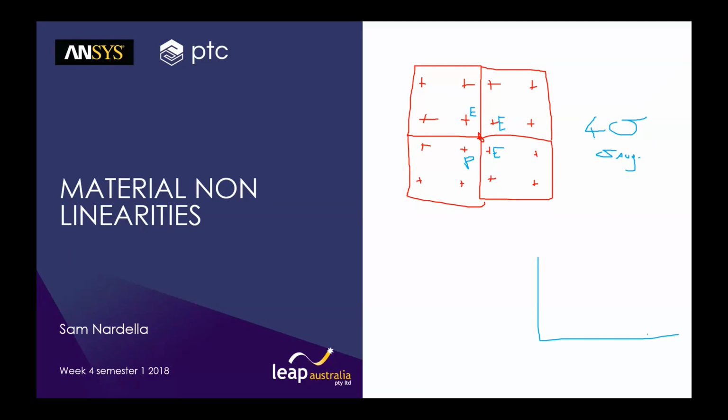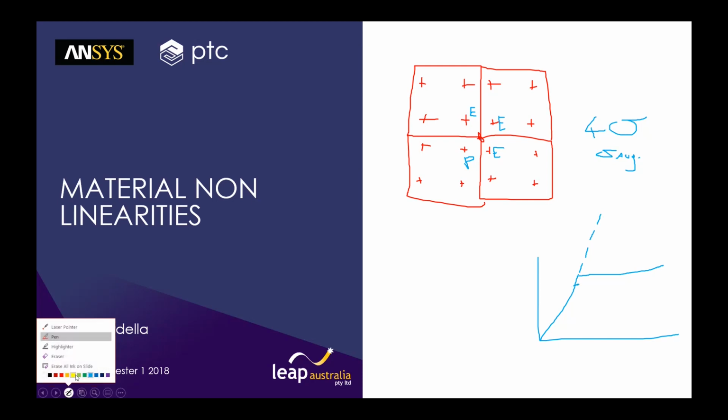So if this is our stress strain curve, just drawing an elastic extension. So this is the integration point stress. But when we extrapolate, we get a stress somewhere up here. So let's say that all three of these elastic stress states were this value, and the plastic stress is here.